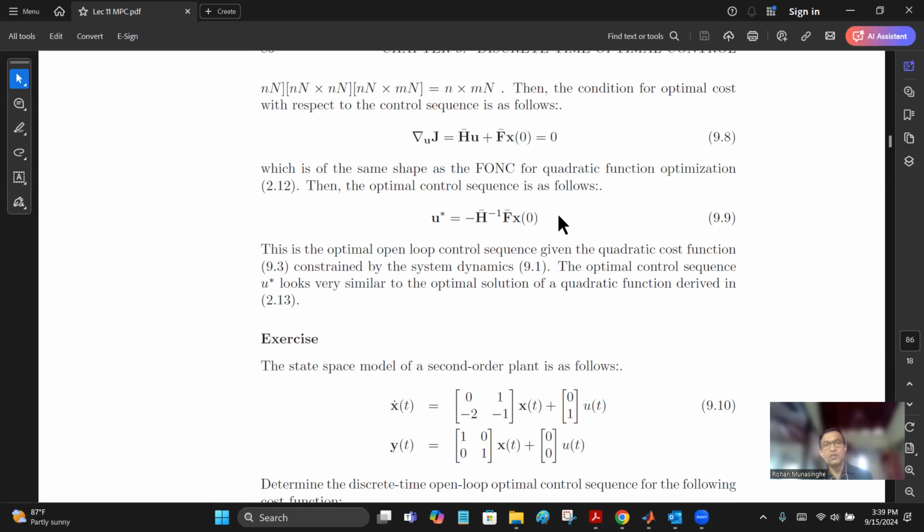So we don't need to give this minus and inverse and all these things, right? Because quadprog is designed for that, right? It is coming from this optimization actually, okay, more than from here. So if you have this kind of optimization coming from a quadratic objective function, right? You only need the two terms here, H bar and F bar x zero.